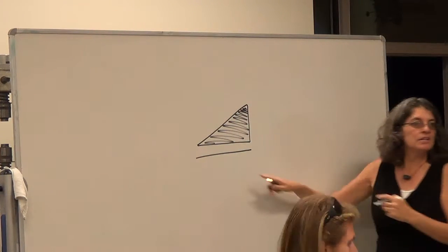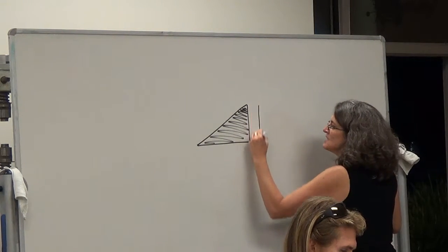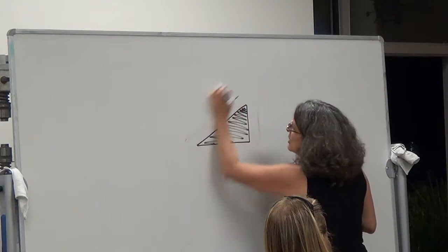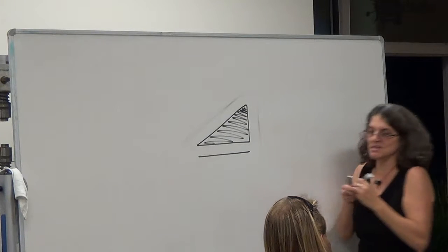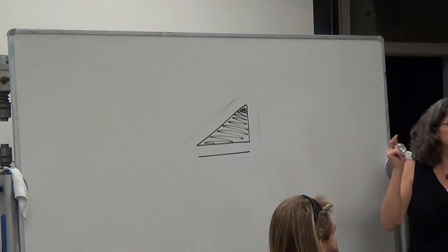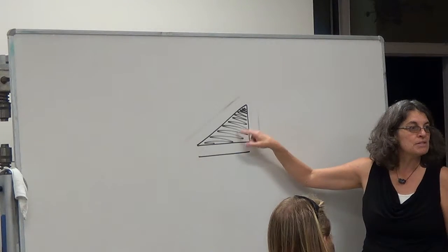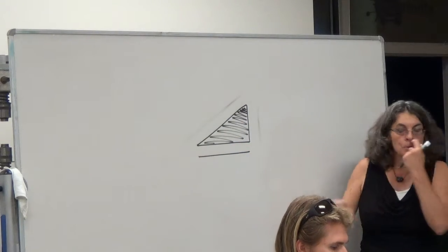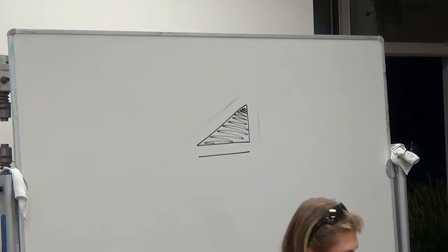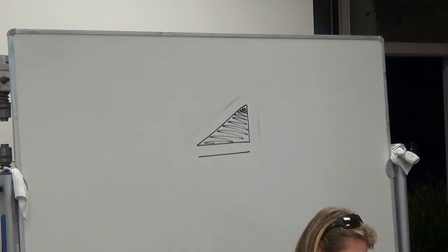So if this is lit, what kind of distance do you think you're reading? Horizontal. Or you get this and it's vertical, or this, slope. So depending on what you have it on, if you press the button to get the distance, it's going to go, and then it's going to beep, and then you're going to know you get the horizontal distance. Then you press the button, and then it'll give you the vertical. Press the button, get the slope. So you are clicking the button to turn it, and then on that readout, it'll show you whether it's the vertical, the horizontal, or the slope.